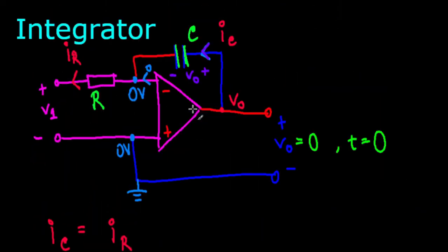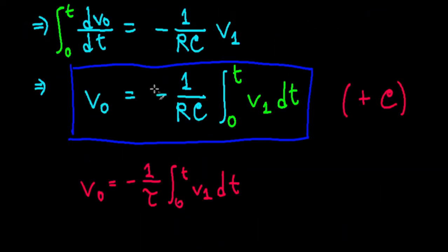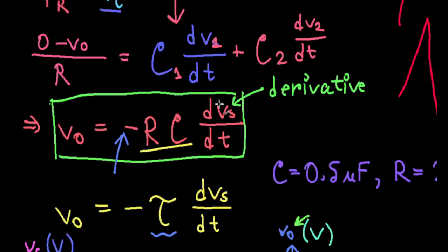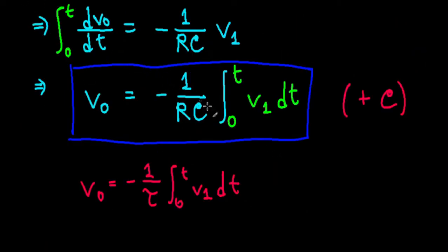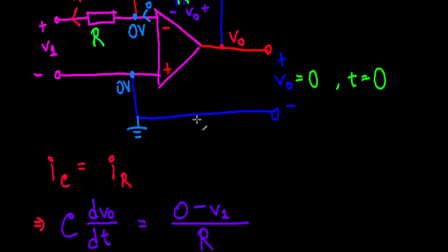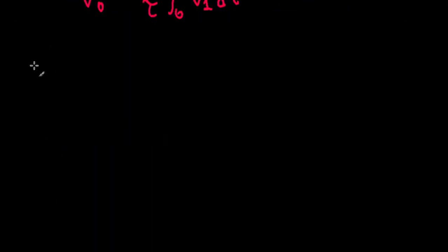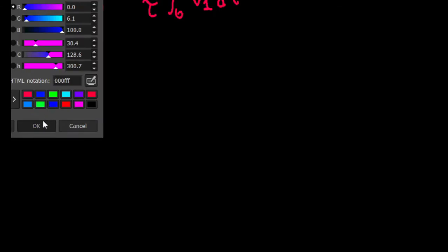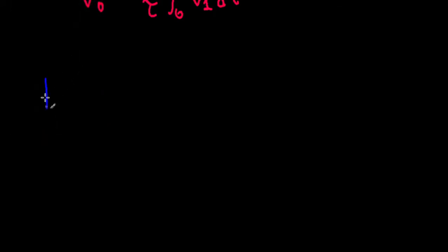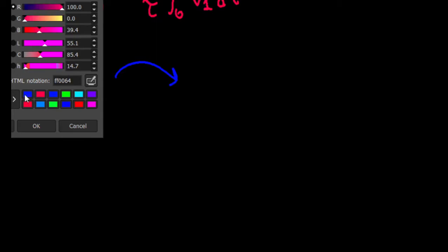So if for these two circuits R and C are the same, obviously the positions are different, these two formulas do exactly the opposite thing. In other words, they are inverse functions. So suppose you take an output from a differentiator and pass it to an integrator. You're actually going to just get your original signal back.